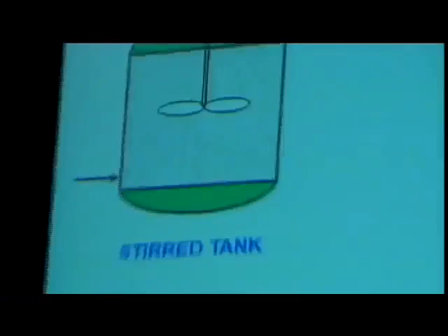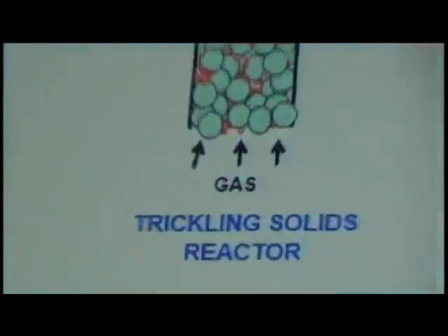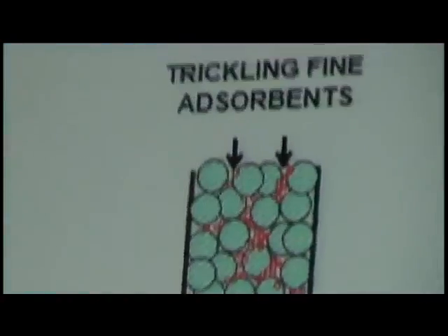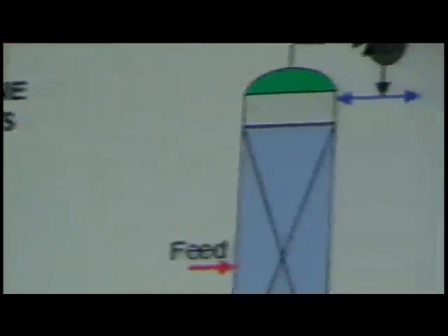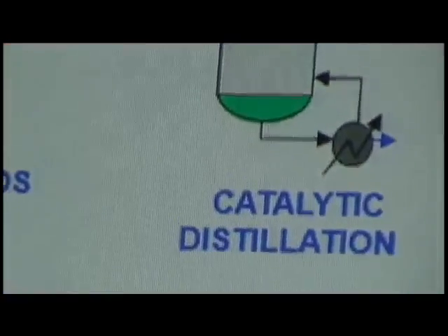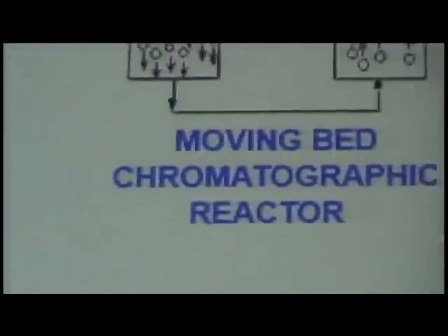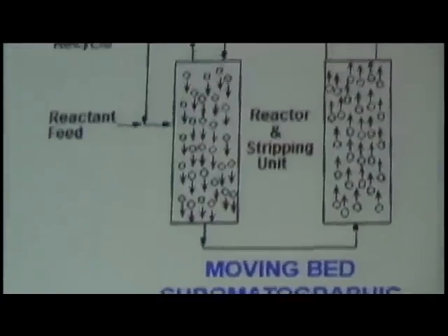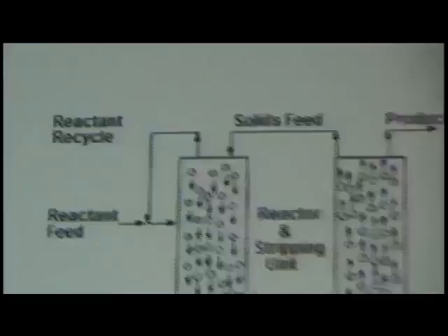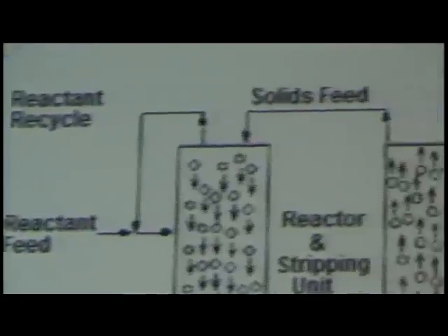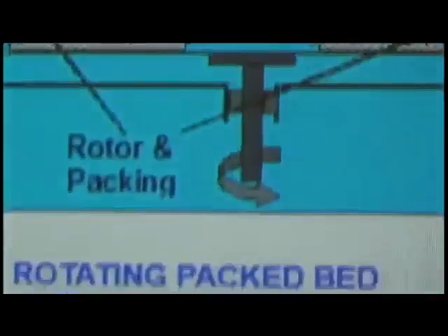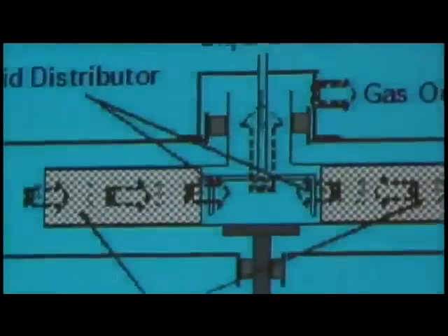I'm looking at also other types of multi-phase reactors with catalytic materials. We have the conventional stir tank, which may involve the use of slurries, for example, small powder catalyst or homogeneous catalyst. Praxair developed the liquid oxidation reactor. It was an attempt to replace existing stir tank technology for producing terephthalic acid from the air oxidation of paraxylene.